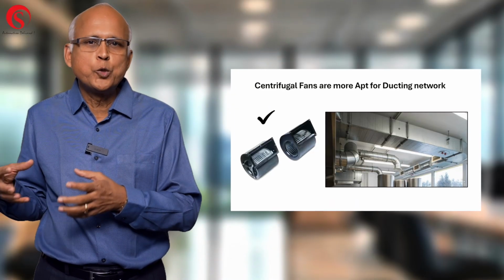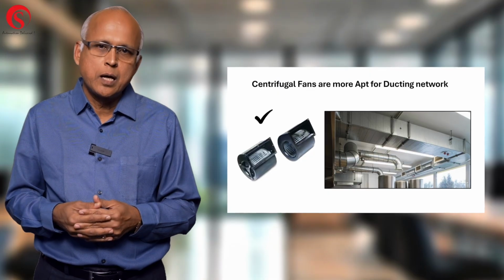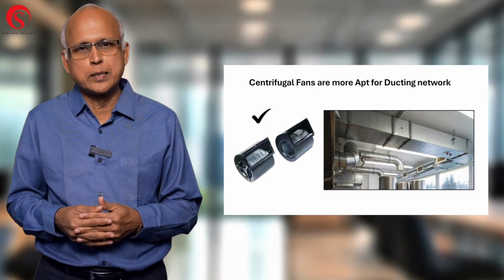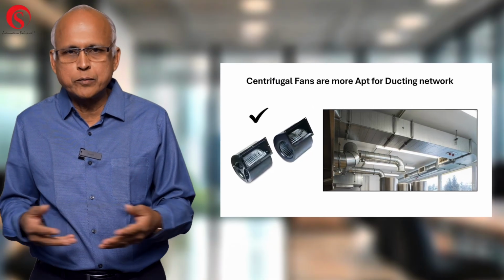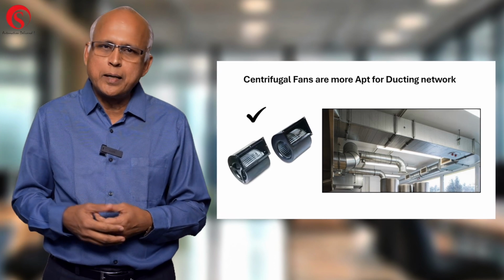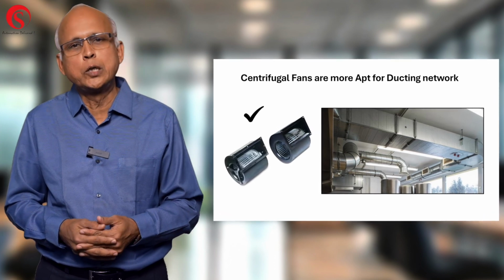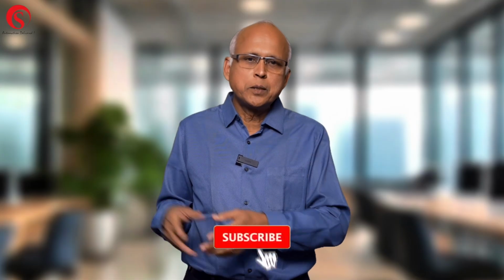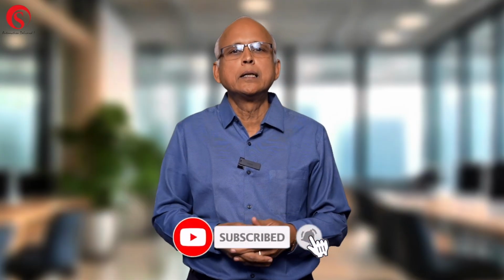In such cases the fans are generally centrifugal fans. Centrifugal fans can generate whatever static pressure we require and deliver whatever air volume flow rate we need. So we cannot simply put a duct on an existing air to water heat pump and take it to a space. It will lead to deteriorating performance of the hot water generation.